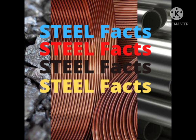Whereas in the electric arc furnace route, the primary raw materials are steel scrap, direct reduced iron and/or hot metal, and electricity to produce 1,000 kg of crude steel. EAF routes use roughly 710 kg of steel scrap, 586 kg of iron ore, 150 kg of coal, 88 kg of limestone, and 2.3 GJ of electricity. Also, did you know that a basic oxygen furnace can be charged with as much as 30% scrap?